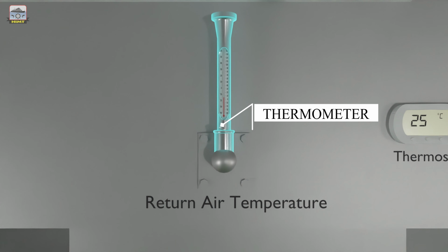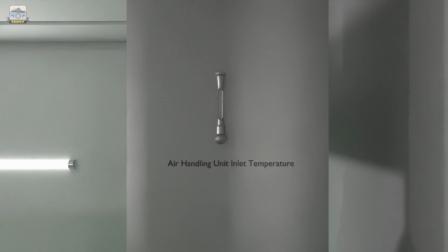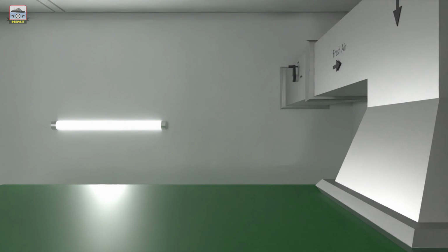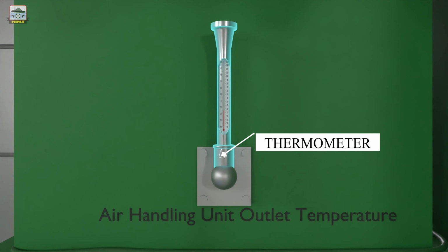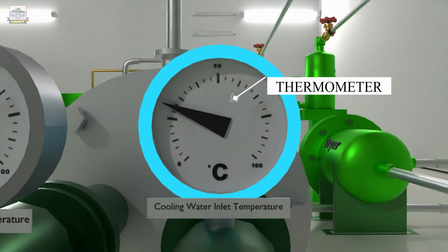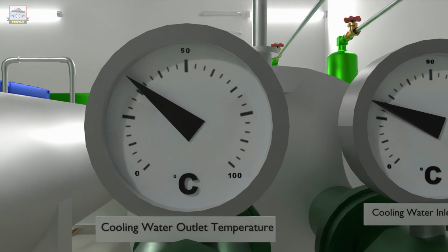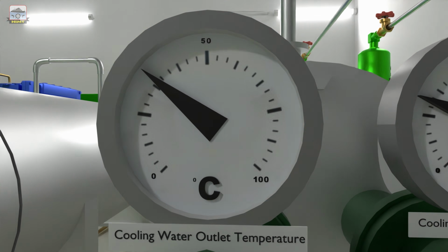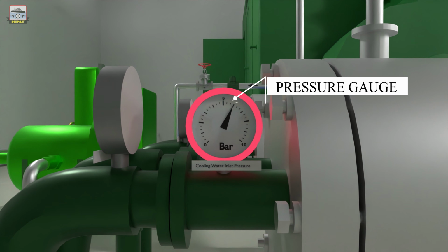A thermometer at the return air duct. A thermometer at the inlet to the air handling unit. A thermometer at the outlet of the air handling unit. A thermometer at the cooling water inlet to the condenser. A thermometer at the cooling water outlet of the condenser. A pressure gauge at the cooling water inlet to the condenser.